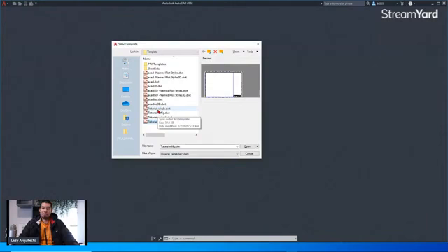many other people teach you about units and that you need to first set up your units. But in order to work efficiently, you need to pick the template that you need so you can avoid setting up your units and wasting time setting those units. There are three main templates that you need to worry about here. The first one, the tutorial iArch, is an architecture template in imperial units.